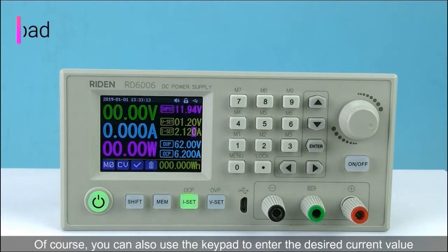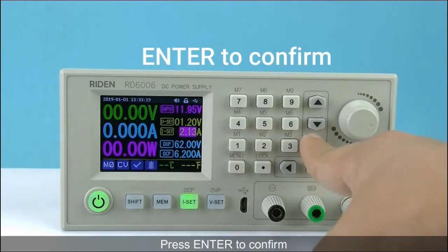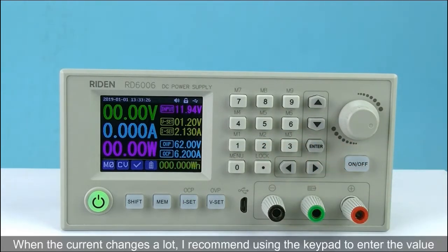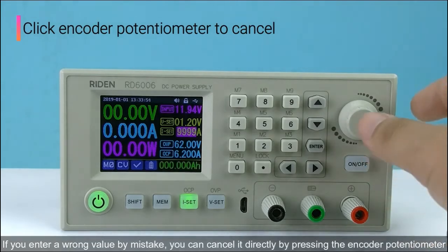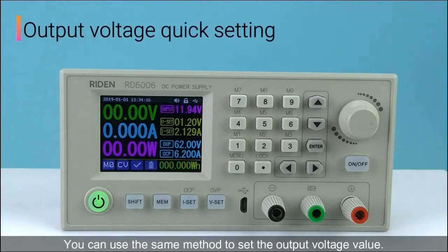Of course, you can also use the keypad to enter the desired current value. Press Enter to confirm. When the current changes a lot, I recommend using the keypad to enter the value. If you enter a wrong value by mistake, you can cancel it directly by pressing the encoder potentiometer. You can use the same method to set the output voltage value.